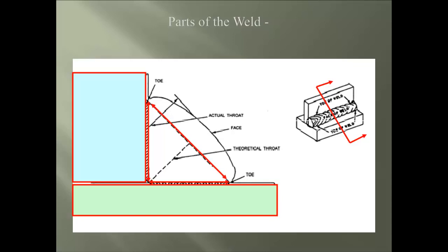So now the fillet weld size is determined by the length of each weld leg. So measure the vertical leg at what is called the toe, and then the same location of the horizontal leg. And whichever leg is the shortest will be the weld size. Now in some cases you could be using an uneven fillet weld, that will have you measuring each leg separately from the other.